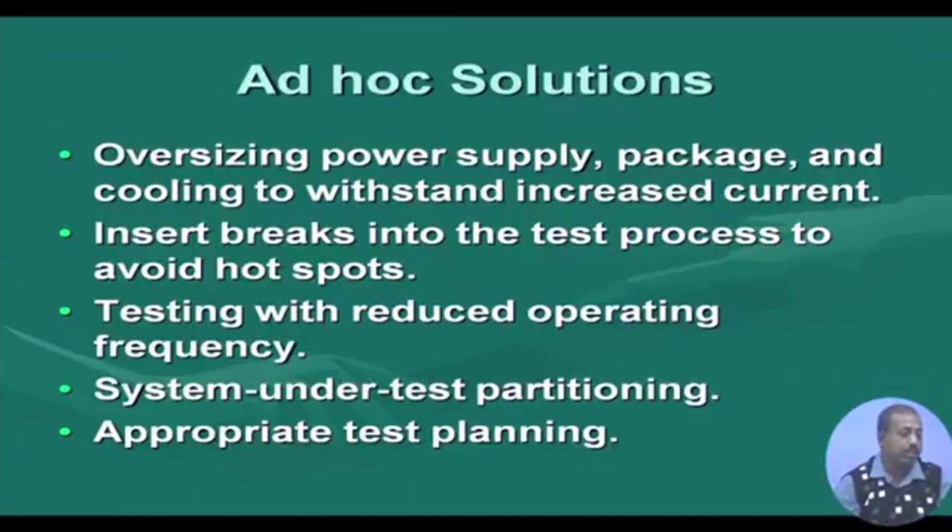Another solution is to insert breaks in the test process to avoid hot spots. If the circuit is tested continually, and if one region of the circuit is excited throughout the test session, then that part will become hot. So, that creates some hot spots in the circuit. So, what we do, we break the test session.